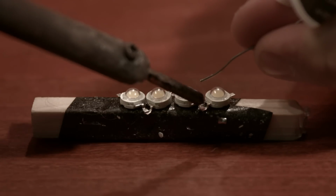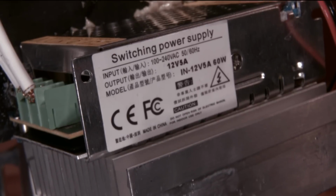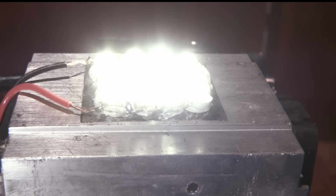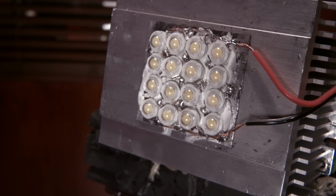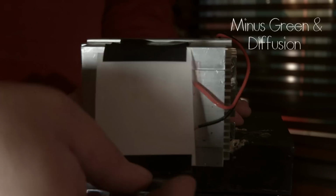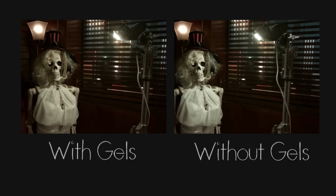I soldered together 4 sets of 4 bulbs each and connected it to a 12-volt LED driver that's 16 watts, pulling a little over 1 amp. Now, these little buggers can create a lot of heat, so I rummaged around a junkyard and bought a used CPU heatsink and cemented the bulbs using heatsink grease glue. Now, these warm white LEDs tend to glow a little bit on the green side, so I attached a piece of minus green gel, which is magenta, and a diffuser on top.